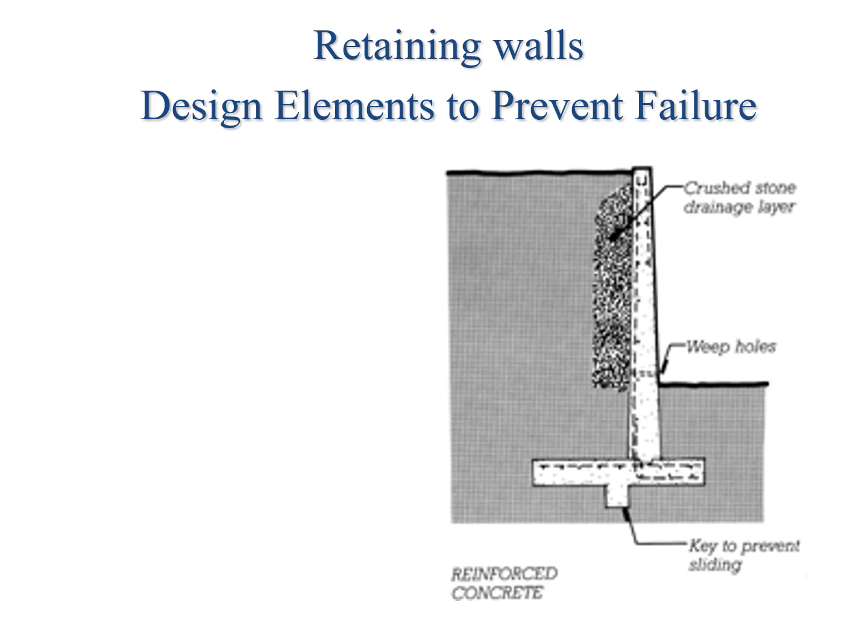You see a lot of these walls, even all the way up, they actually place pipes in them, so it's allowing the water to always go through the earth. If it soaks into the earth, it doesn't just stay there and build up extra weight. The water adds a lot of weight to the soil that's being retained. Instead, it can just pass through the wall and weep out or just drip out in different areas.